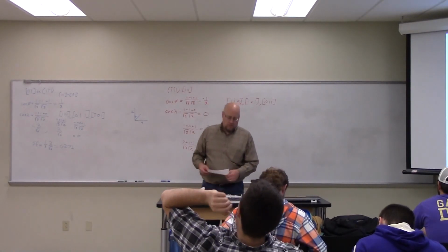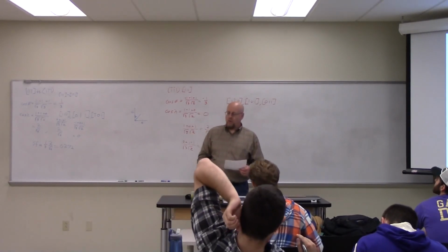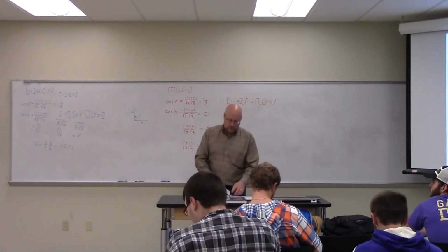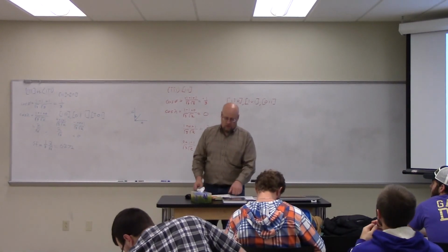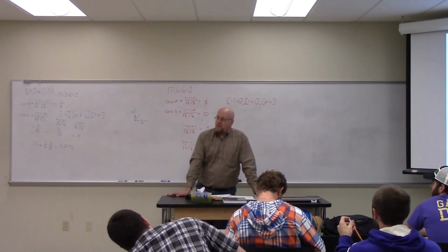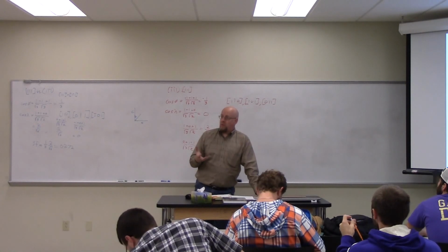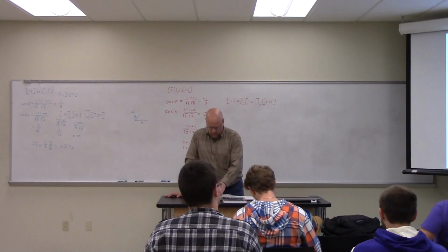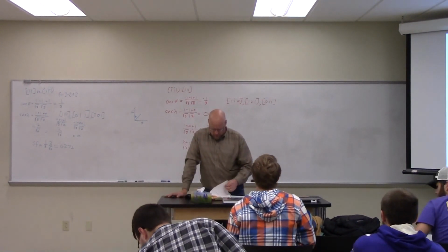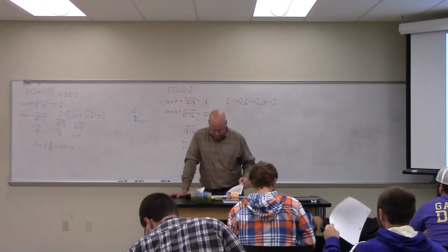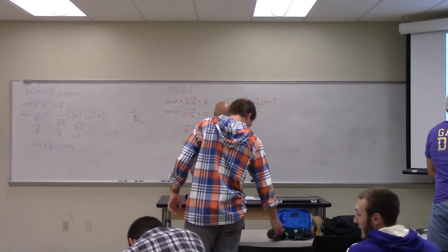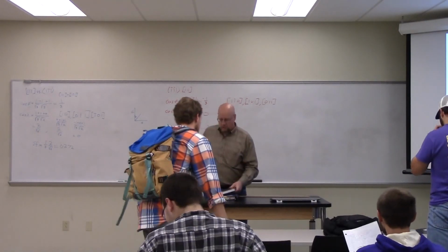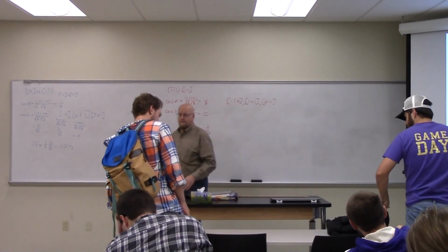And it's probably not random, it's probably got more to do with where the dislocations or vacancies are, and actually it'll be a combination of them, because in reality, when a dislocation encounters a vacancy, it can pin the dislocation because there's extra strain associated with the vacancy already. I don't know if we'll talk about that at some point or not. It seems to me we probably should, but I can't remember. Anyway, it just depends on the statistical distribution of things and the actual crystal. Now we can talk about it because we're a day ahead.